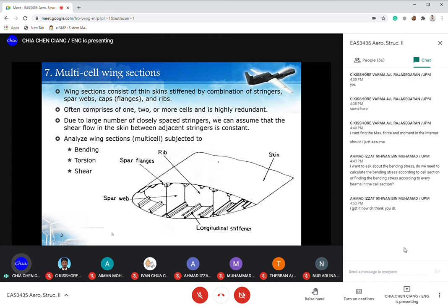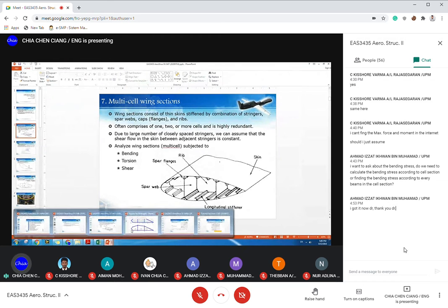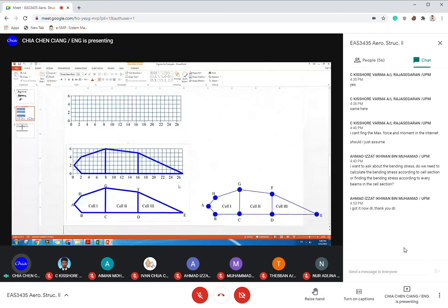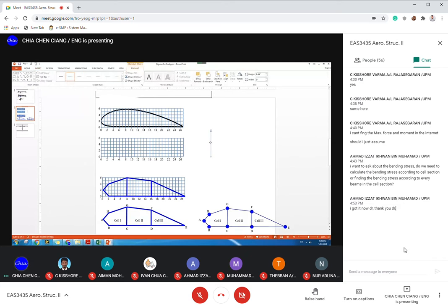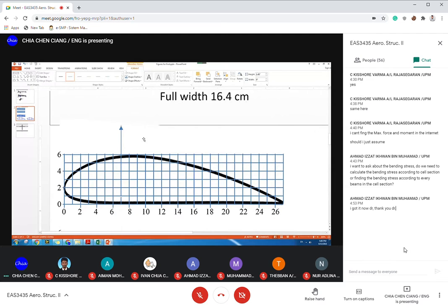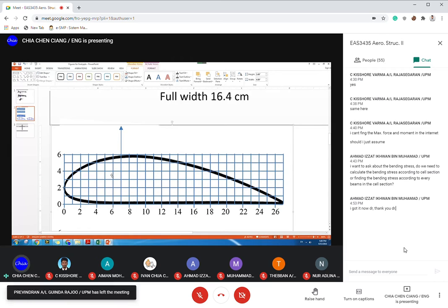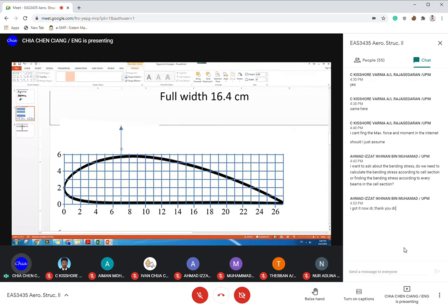So if you draw from the cross-sectional direction like this, eventually the lift force will be just one arrow, near the quarter chord. Even supposing it's distributed over the area, we can simplify it. We do the integration and simplify it as a distributed force near the quarter chord. This is not a point force, it's distributed along the quarter chord.